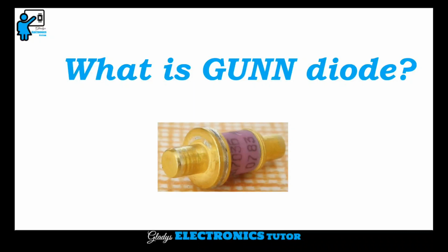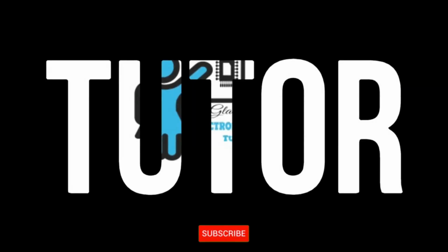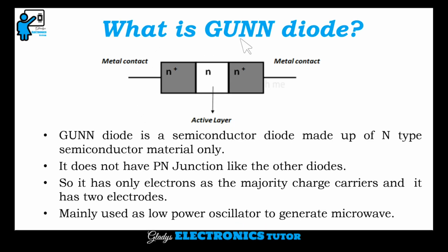In this video, let's see what is Gunn diode. What is Gunn diode? So Gunn diode is a semiconductor diode made up of N-type semiconductor material only. It does not have a PN junction like the other diodes. So it has only electrons as the majority charge carriers and it has two electrodes. Mainly it is used as a low power oscillator to generate microwaves.